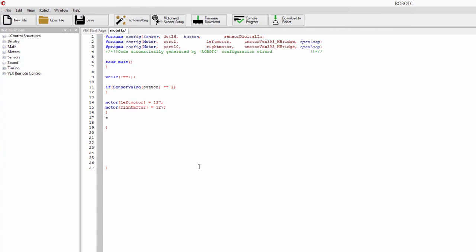So we're going to write a statement that is else. Else is going to happen if the if doesn't happen. Else, enter, squiggly bracket, enter, and we need to write motor, or actually instead of writing it, we can just copy these. So select these two, right click, copy, and inside that else, after that little squiggly bracket, right click and paste. Okay? Else, motor left, the speed is going to go to 0. So that means it's not going to move. And motor right is going to go 0 as well. After that, after motor right, press enter once and close off the squiggly bracket.